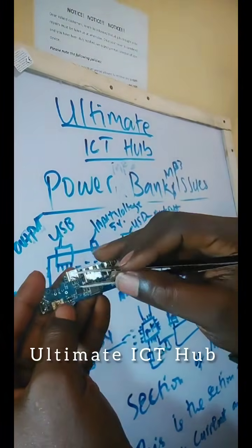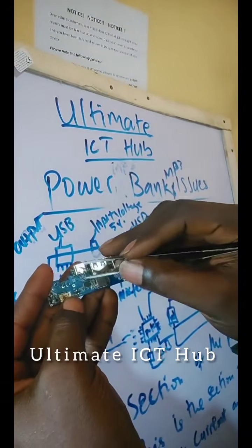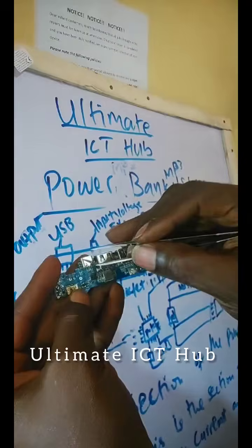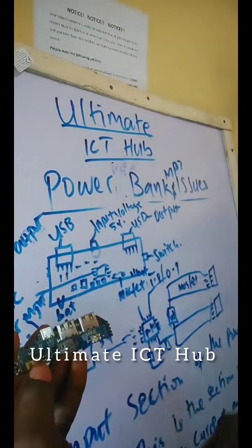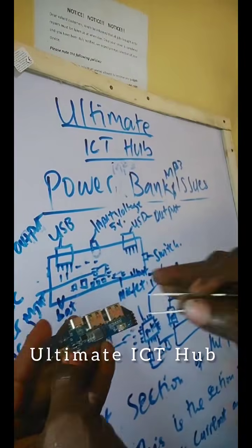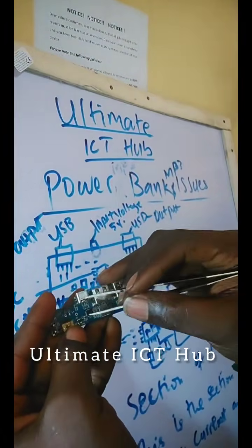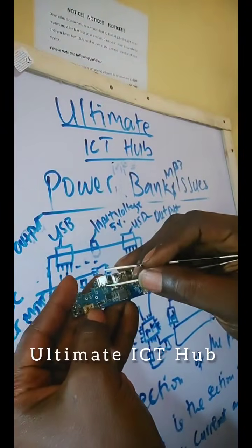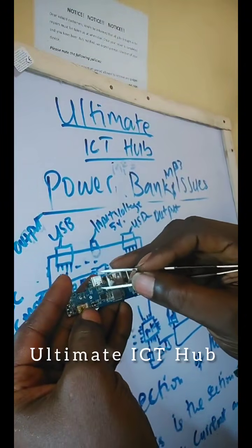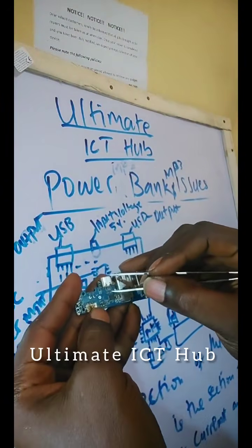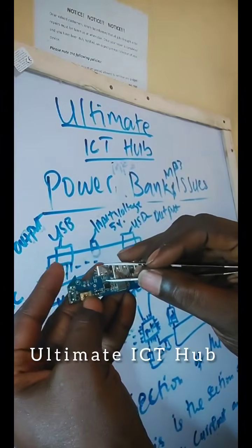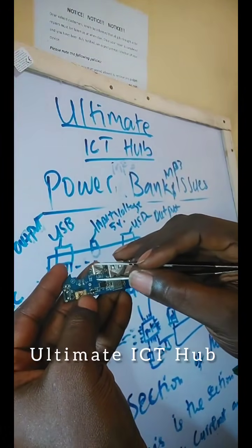So if this thing gets damaged, what happens? There is one of these capacitors or fuse resistors that is faulty, or that is short. You understand? So damage to any of this brings damage to this, because one of those things will not be regulating the current again. Then it brings too much load on the remaining 3.